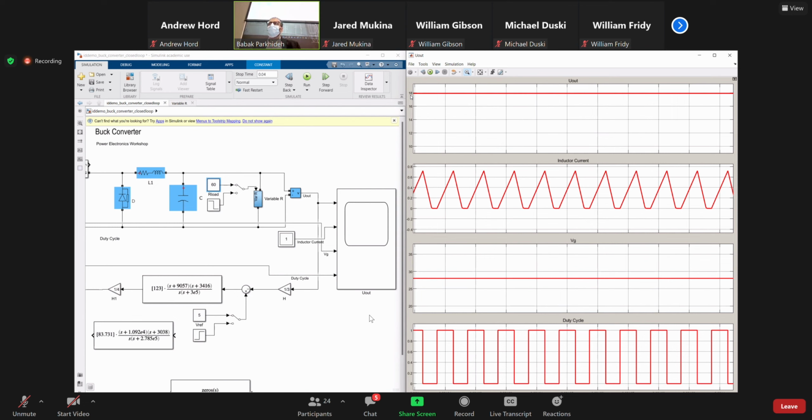So in other words, you may have to burn some energy to keep this converter working. So perhaps if you design any board or any system or pick any power supplies, small or big, you see that it has a minimum load requirement and you terminate it with a resistor, depending how much power it wants to tolerate, to actually make it adaptable or make it practical for your applications. Because essentially, you have two converters, one at low load and one at nominal.